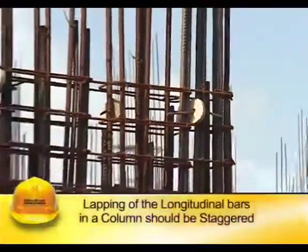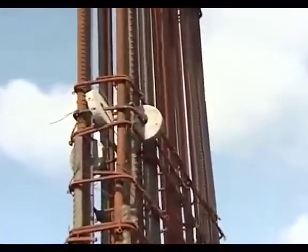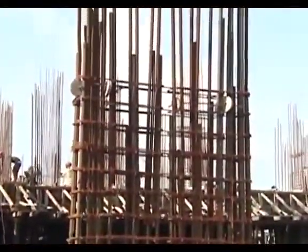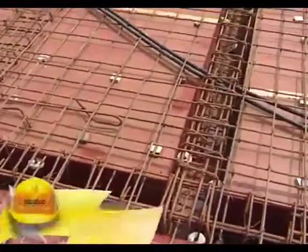The lapping of the longitudinal bars in a column should be staggered and not more than 50% of the bars shall be lapped at any location. Lapping can be done by tying the vertical rods with lap length as per design, or 2 rods can be welded to save on lap length. In columns and beams, the length of lap shall be as per design.